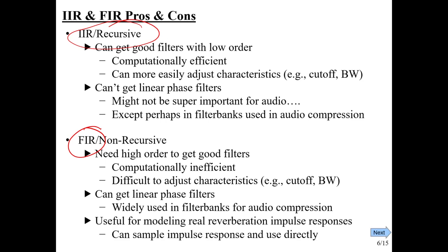And so that's what I'm saying here. FIR filters are very useful for modeling real reverb impulse responses. And so we really can go to a room and measure its impulse response. Now, technically, that room is an IIR. It will actually theoretically have an impulse response that would last forever.